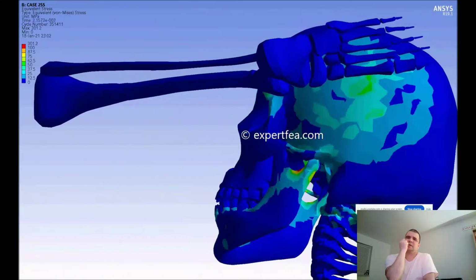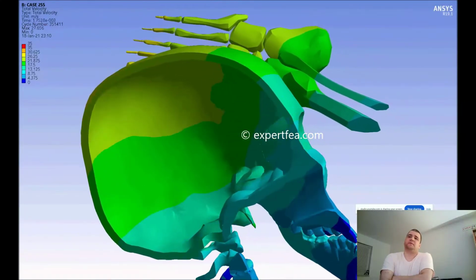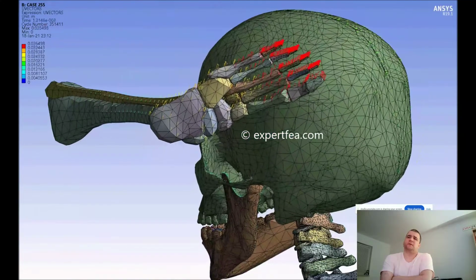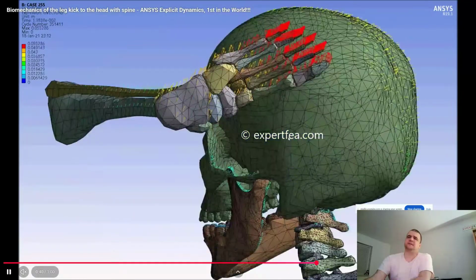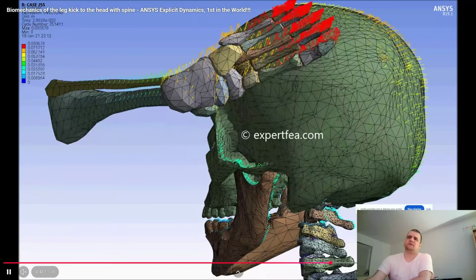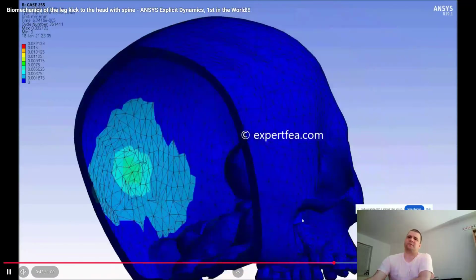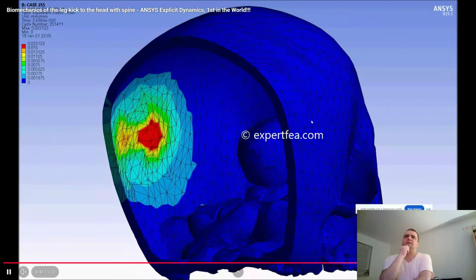It was very complex to make the 3D model meshable. Lots of work. Here is kind of breaking. The disc is too soft, and I didn't assign a pinball radius to cover most of the disc, so it's only touching in a small portion. This is why it kind of flies away from here. So yeah, I will do better next time.